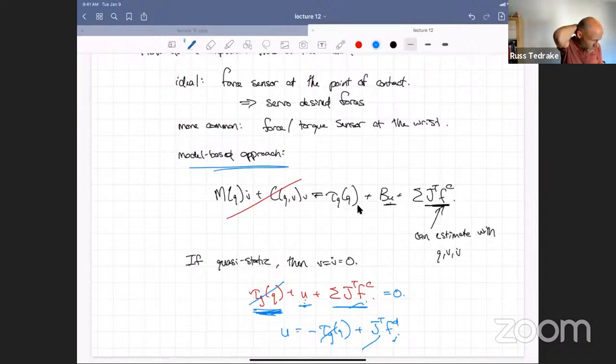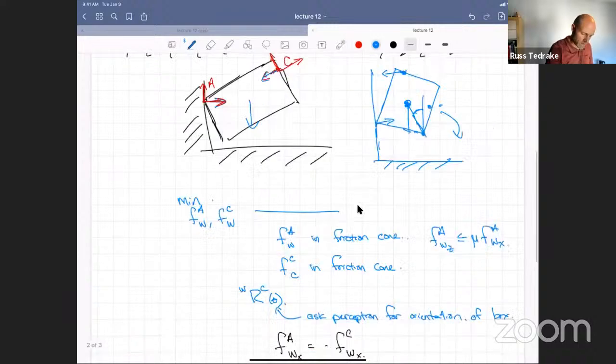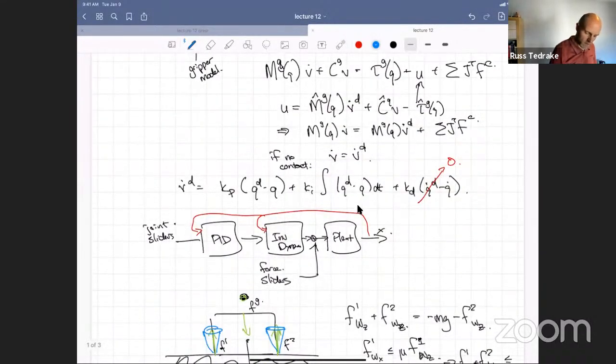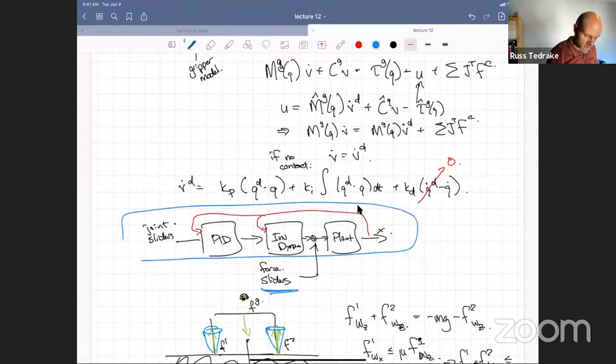In practice, what we tend to do with the KUKA, for instance, the KUKA push in the book, it was a combination of the joint and the end effector control. So we have Kp plus Kd, whatever, for the joints. We planned a motion to put the hand into contact, and then we added, just like I said way back in the beginning, what you did in your teleop. We just used this interface. We said everything's going well here up until we got into contact. And then we just added a little, not with sliders, of course, but with a controller that added force directly in as just a feedforward extra torque to then regulate the force on the book and push the thing sideways.